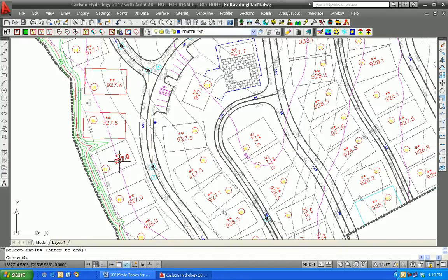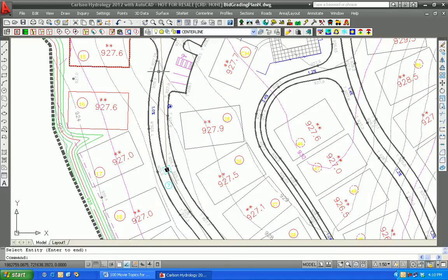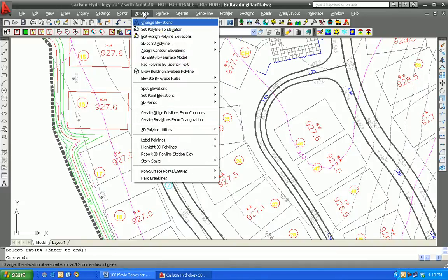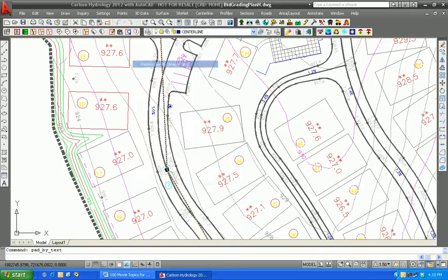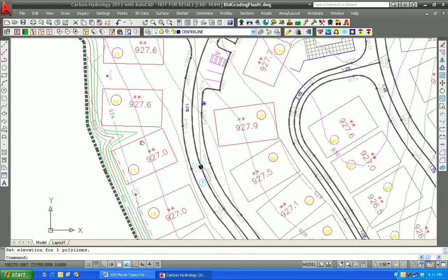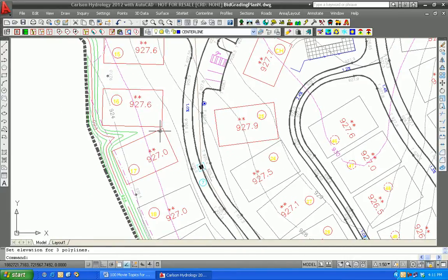Now, if you go to List Elevation under Inquiry, you'll see that the elevations of the pad were raised. And we'll repeat it for the pad 17, 927, just to illustrate the command. Select OK. One selection here, one selection here, no others. And pick the ones you want to do this to. You can actually pick any number you want at this point, and all of those get raised. Now what we want to illustrate here is that you can do multiple pads at the same time.